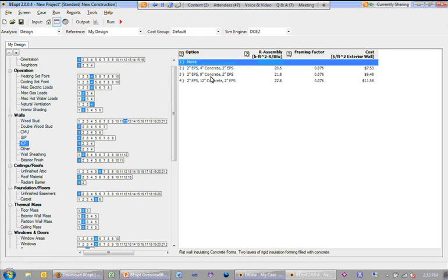The thought I would have on that is that if you were in a situation where you had a significant deadband, or range, between the heating set point and the cooling set point, and your diurnal outdoor temperature fluctuations were such that you were not purely in heating mode or cooling mode, that would be the circumstance under which you would expect to see the most effect. If that makes sense.